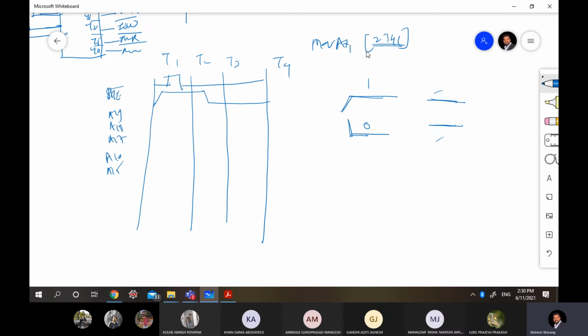Now this is the address 2341. Let's suppose the base address is 5000, so the actual address is 52341. This will expand; understand what is actually happening. I am going into a little detail, only as much as required. 5 is 0101, 2 is 0010, 3 is 0011, 4 is 0100, and 1 is 0001. Now this is the address. This is what A19 has to carry, this is what A18 has to carry, and likewise up to A0.